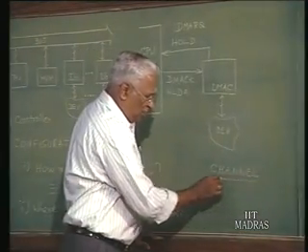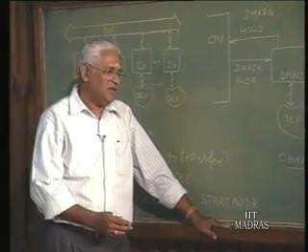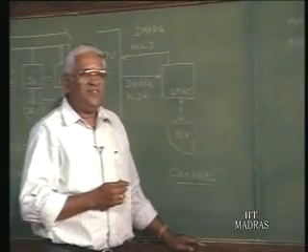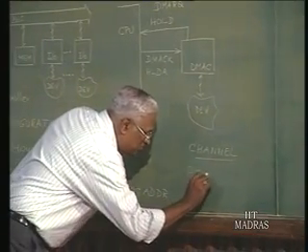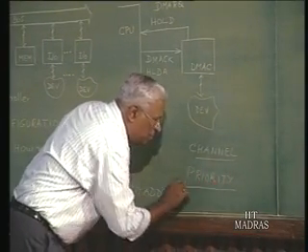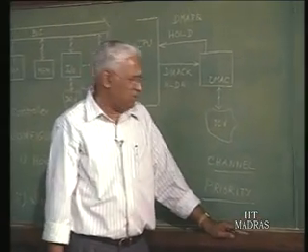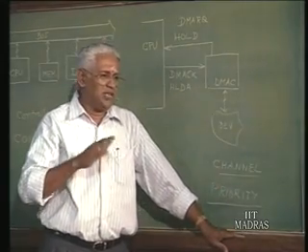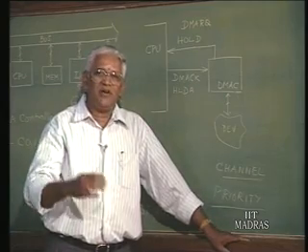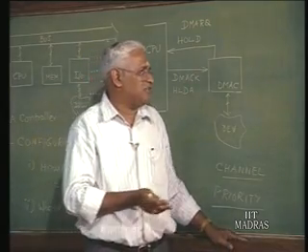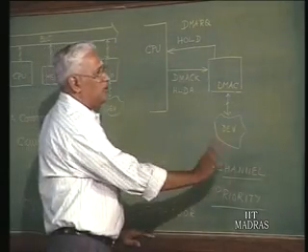Then when you have 4 channels, then what is it? We have come across this situation earlier, no. Let us say if there are 4 devices interrupting, then we talk about priority. The same issue comes here too. You have to look into the priority among the 4 channels. Normally this will be built in, saying channel 1 is a higher priority than channel 2, which is a higher priority than channel 3, and so on and so forth. But then one can change the priority also. We have talked about it earlier in the case of interrupts, right? That is called software definable priority, right? Good. So, these are all certain additional things.